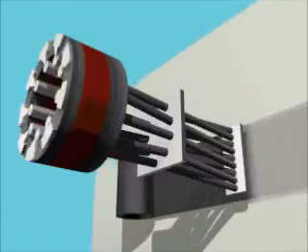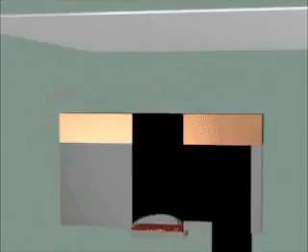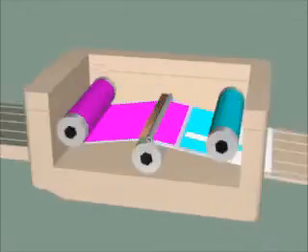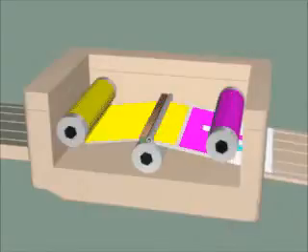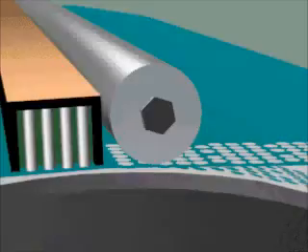Other printers receive the same types of instructions as a laser printer, but they put ink on the page in different ways. A dot matrix printer has metal pins connected to electromagnets. The magnets push the pins against an ink ribbon, leaving a series of dots on the paper. An inkjet printer has tiny heating elements that heat a drop of ink so that it expands into a bubble and finally bursts, shooting the ink onto the paper. A thermal wax transfer printer uses heat to melt wax, colored with inks. Different amounts of red, blue, yellow, and black ink are mixed to create a single full-color image.